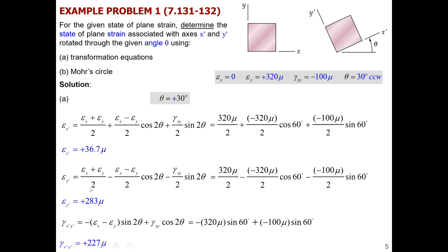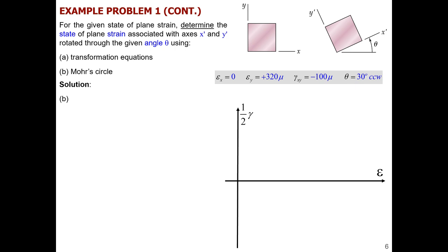So we just used the equations and we obtained all the numbers based on that. Now we want to confirm, or at least look at how that will look if we use the Mohr circle and get some intuition from that. Let's go with it. We will need our coordinate system, in which we don't forget to have this factor of half with gamma. That's how we redefined the Mohr circle equations, through half gamma as a coordinate here. It was more convenient for us to do. Now we remember that.